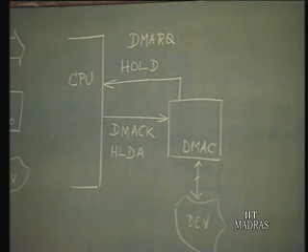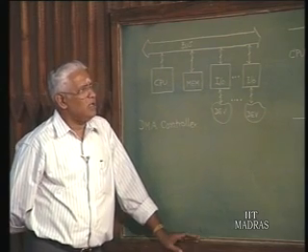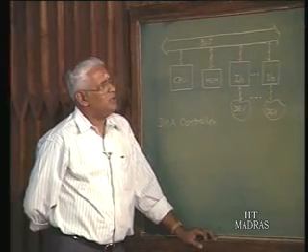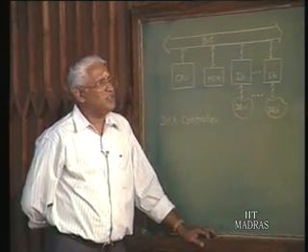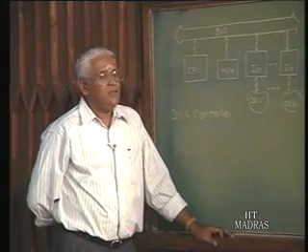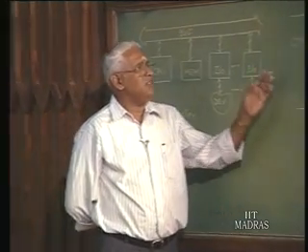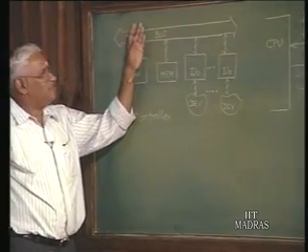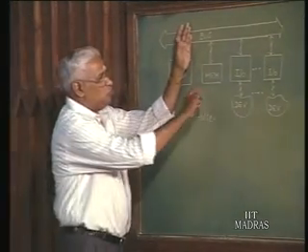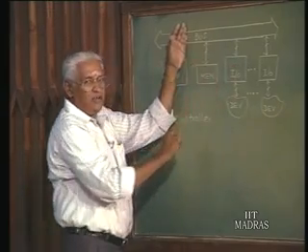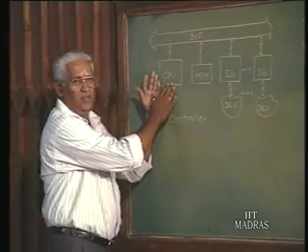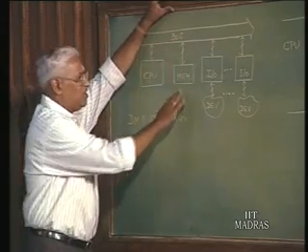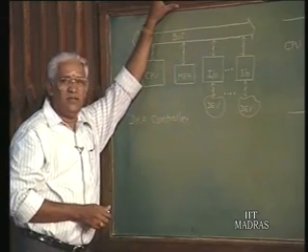Now, if this is the situation, what is the kind of programming that is involved in this, that is the device service routine. After all, the CPU is not involved in the service at all, am I right? The CPU is cut off from the bus. So, it is the DMA controller which takes over the role of CPU and sits as the master of the bus and then regulates, agreed.